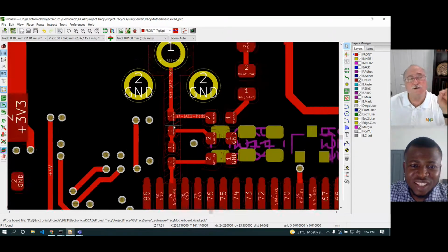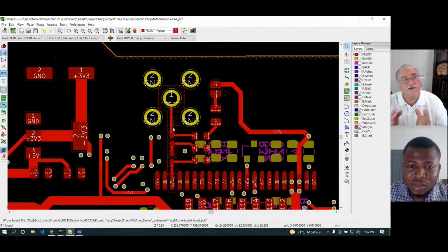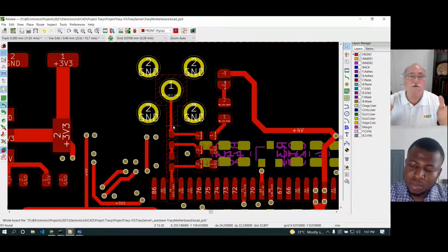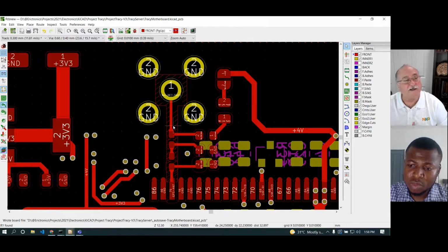These are discontinuities. Again, anytime the wavefront sees a different shape in front of it, it will behave differently. If it's a lower impedance, you will have a drop. It'll have a reflection at a lower voltage. If it's a higher impedance, you'll have a reflection at a higher voltage. But as long as that space is what we call lumped, where you never exceed 100% of the voltage in the reflection, that's why we got away with bad design rules for years.